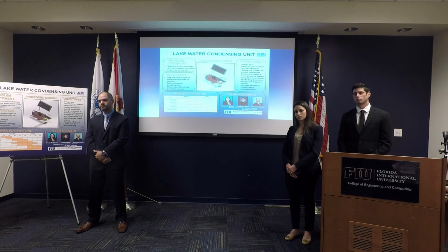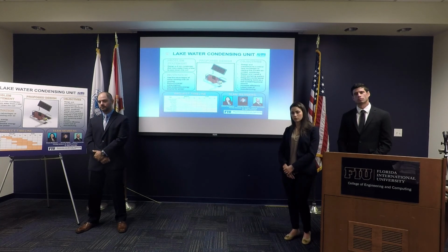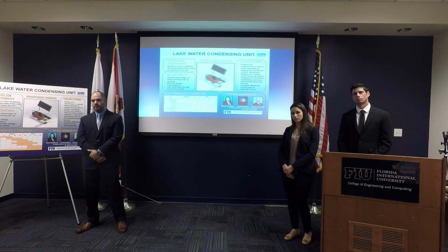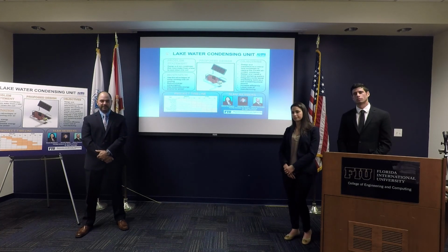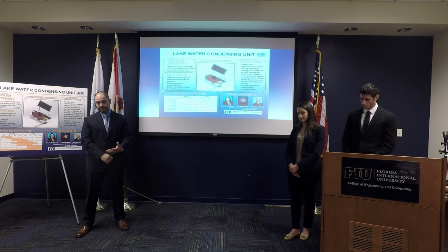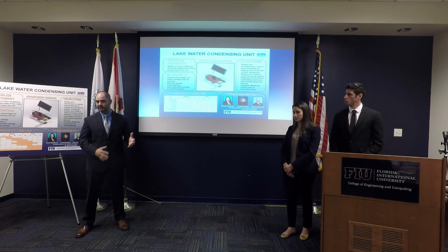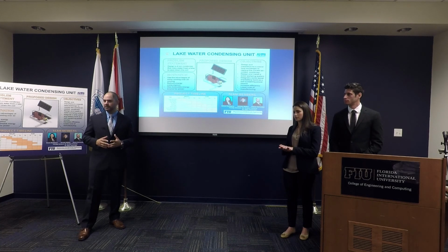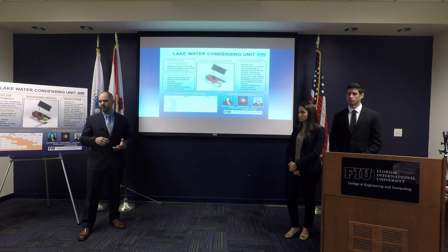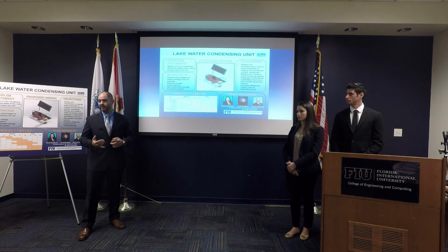And then the last thing is biofouling. What are you going to do to make sure that the system is assured, that you don't get this thing all clogged up? That's a very interesting point. We're in the process of trying to figure out how we'll possibly incorporate a flushing system, just using house water to flush it, either manually or automatically, on a regular basis to make sure that we don't have that.